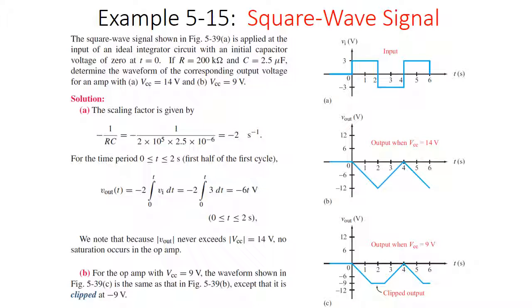Now what happens there, we have a little difference because we're getting beyond the power that the op-amp has. So if the op-amp only has 9 volts of power applied to it, the max signal it can produce is 9 volts. So what happens when you go beyond 9? Well, you just clip the output. The output becomes flat. And so now we get a really kind of cool, complex trapezoidal signal, which is interesting to come out of it. And that happens, again, because our op-amp is at 9 volts. Now, if our op-amp was 12 volts or 50 volts, we wouldn't see that.